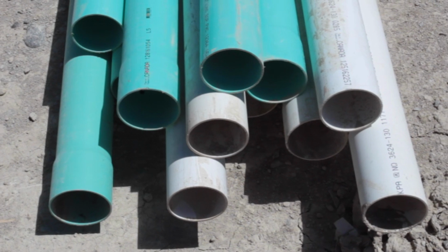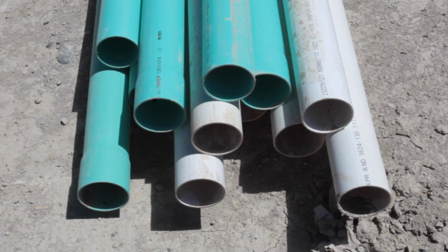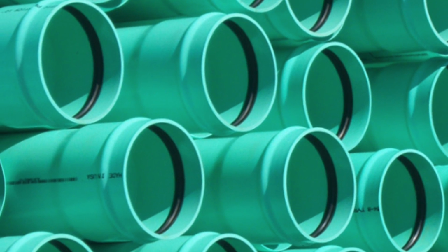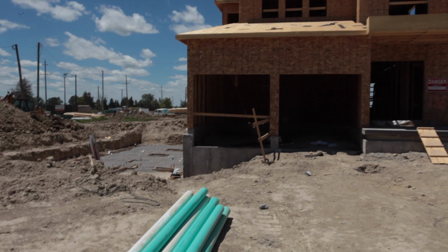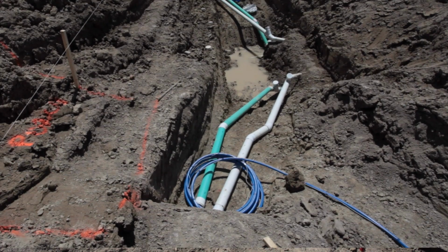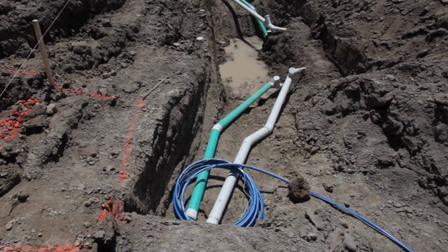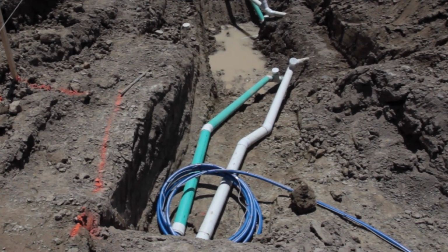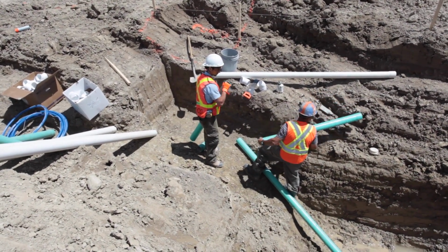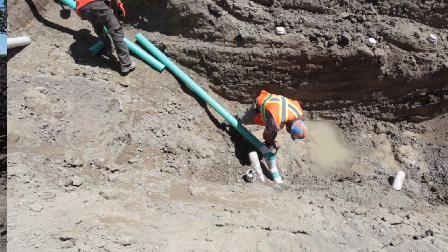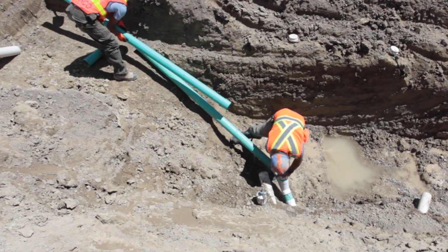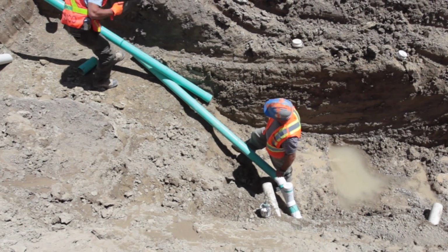The two main types of pipe assemblies used for the installation of exterior sewer laterals are solvent weld and gasketed pipes and fittings. The solvent weld pipe assembly is the most common standard used in the new home building industry. When joining or connecting PVC pipe, all pipes and fittings must always be inspected for defects or damage. Any defective or damaged pipe or fitting should be replaced, and all foreign matter should be removed from the pipe interior. After inspection of the pipe and fittings, we move to the field cutting steps.